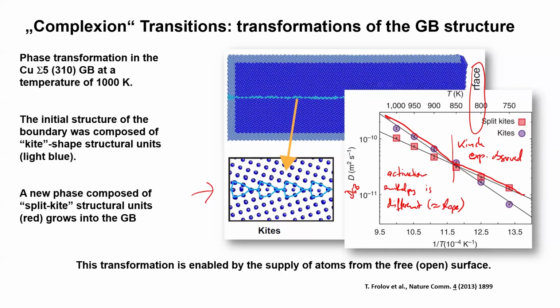but you have different slopes in different temperature regions. But measuring in the zone where the transformation occurs is almost impossible, because that structural transformation would be much quicker as the diffusion experiment would do. Yeah, but then you don't see diffusion. In the computer simulation you could interrupt, but the diffusion is a long time process. The transformation occurs much more quickly. So the characteristic time of the transformation is maybe related to local atomic jumps, but when we analyze diffusion, it's long range transport and not the local jumps.